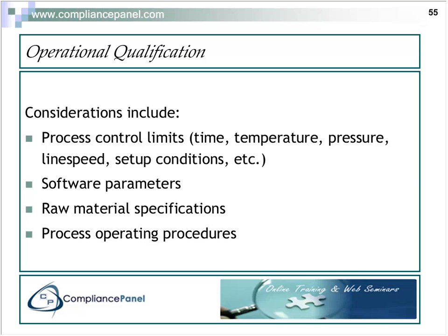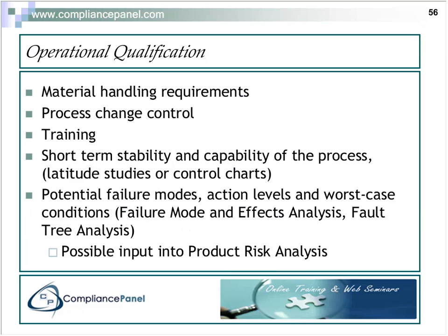And then we also have to have those operating procedures, because we want the operator to follow those procedures and see, in fact, if they do work. Talk about material handling. Process change control. Once we have completed this step here, the OQ, we're going to put our process under change control, and we're not going to allow any changes to be made to that process unless they go through the change control process. We're going to do training of our operators from this point forward.